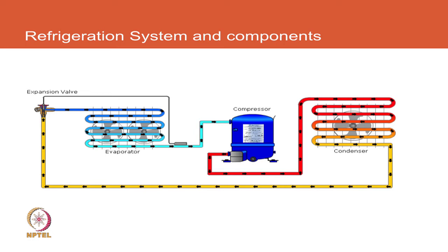So, you looked at the compressor, we can look at the condenser. There again, what amount of heat exchange surface area? So, we design it for a particular temperature, and we talked last time a little bit around the variation that happens in real life. So, we will have temperatures going down to 30 degrees or even lower at night and going to 46 during the day. So, what does it take to have that heat exchange surface suffice for the variety of conditions that we have?